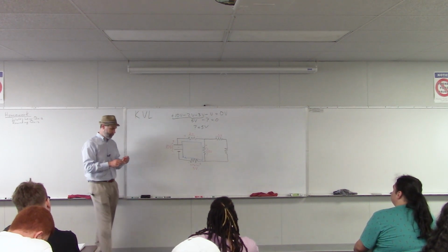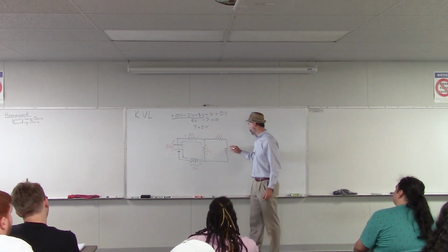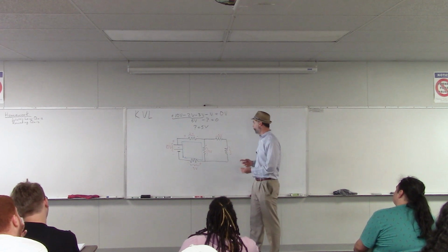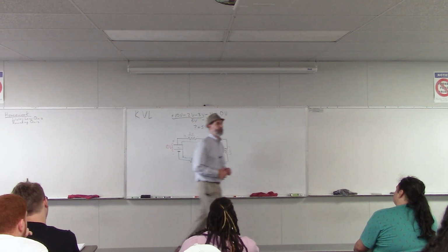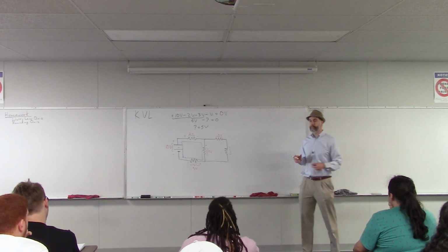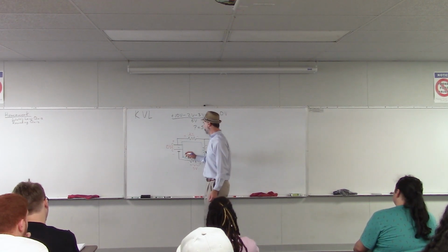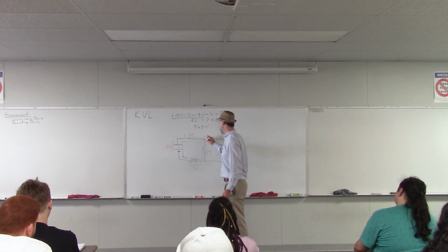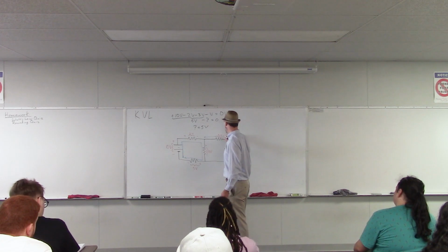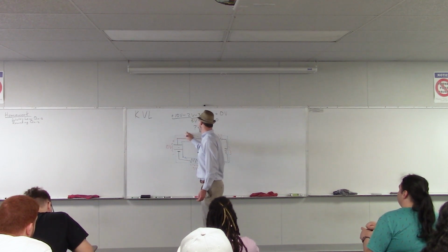Okay. And then we could do a similar thing for this resistor over there. So where could we draw the loop to figure out the voltage across that resistor? Sure, we could do the whole outside. So we could start there again, but just for fun, we could start anywhere. So why don't we start up here? So we go through here, and then down that way, and then around, and end up back where we started.